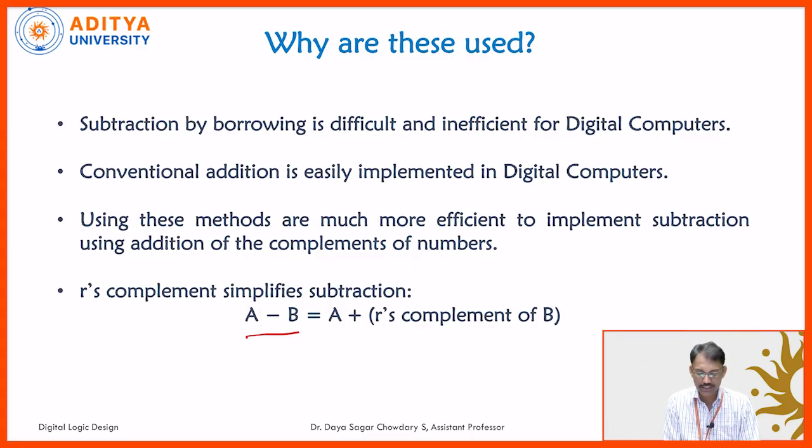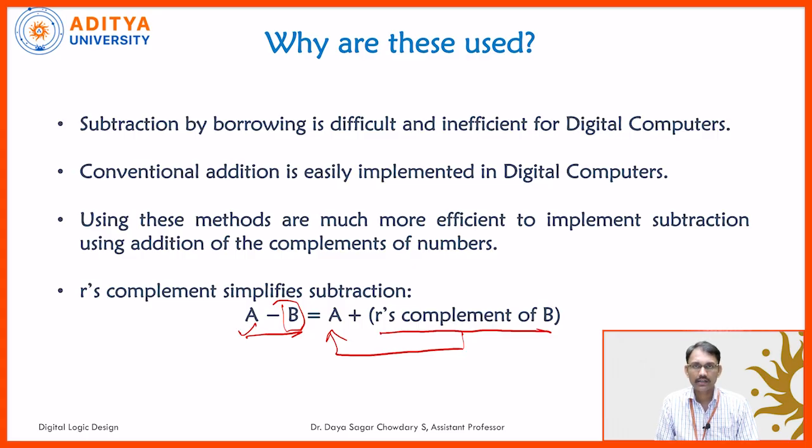So this is the representation. That means if we want to subtract b from a, we simply calculate the r's complement of b and add the result to a. So this is the trick for performing subtraction in digital computers or any digital equipment.